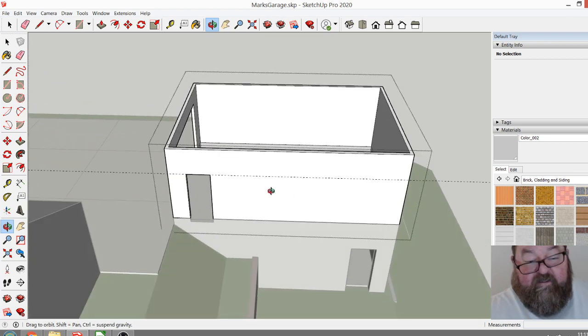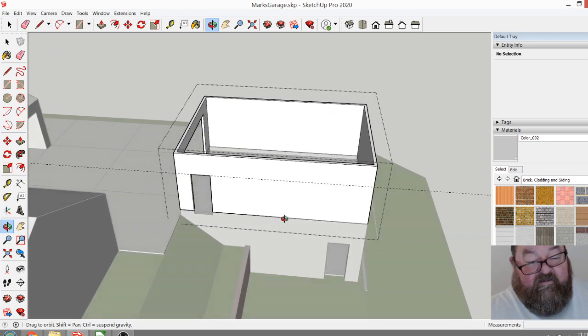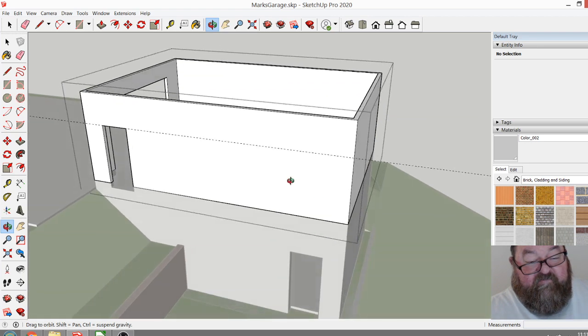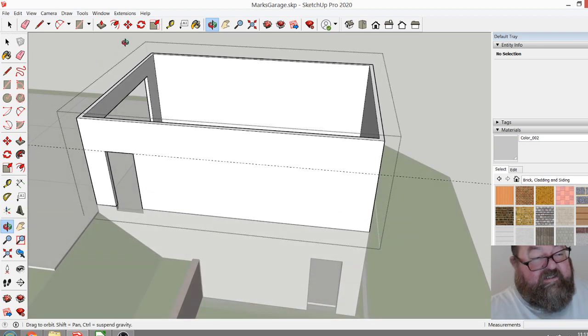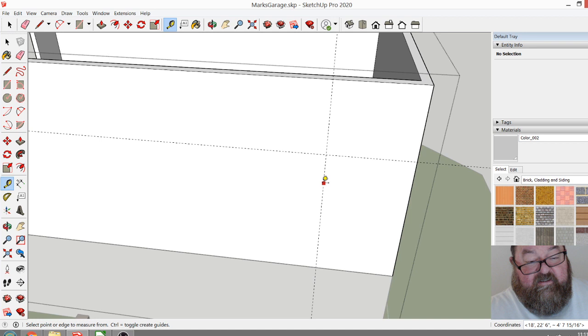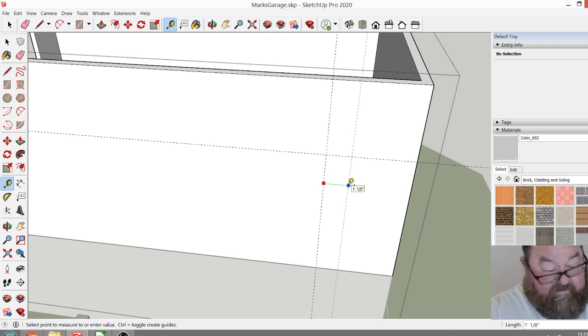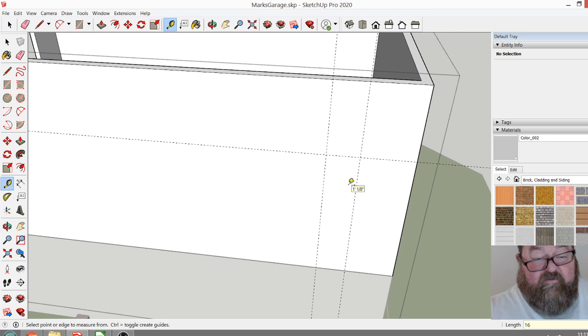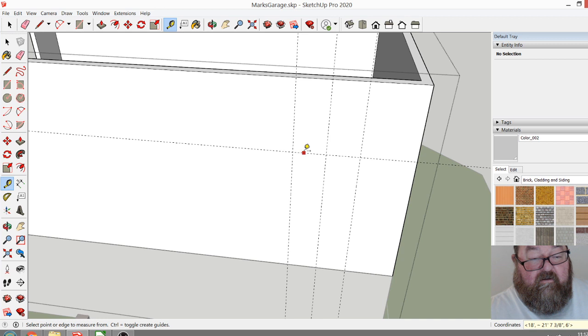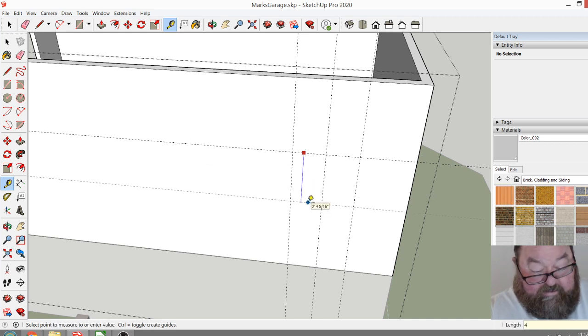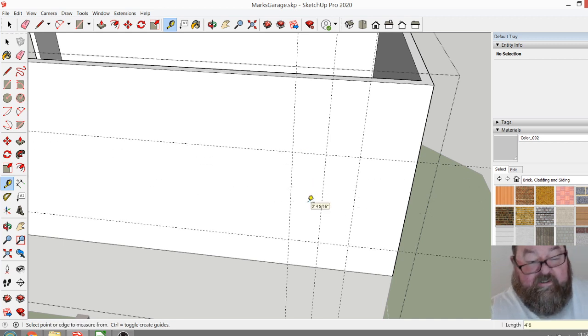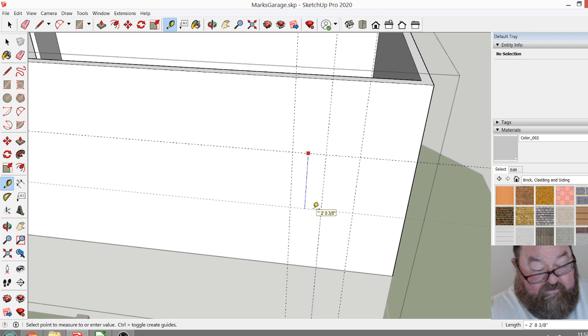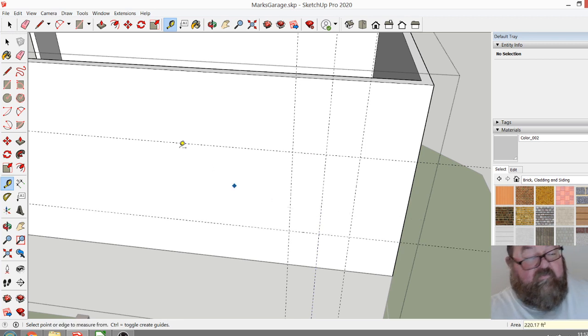Well, actually, I could have left that. That would be my window height. And then, if you wanted to be consistent, this could line up over that. And again, we could have a 32-inch opening there, a 32-inch window, 16, and we'll do 4'6" for now, which is kind of typical. That's a little bit big, isn't it? Again, that's what this is about. That's 4 feet there.